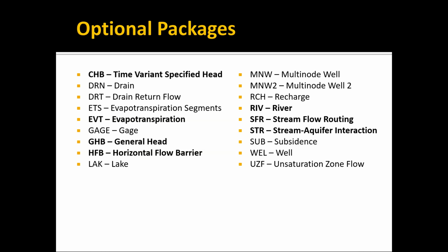If the water table drops too low, it may cut back. Instead of the well going dry, it cuts back the pumping rate. In addition to specifying a pumping rate, you can have a pressure defined well. So instead of telling it how much water comes out, you tell it what the pressure is, the suction on the well, and then it determines how much water comes out. In a lot of cases, you don't need that sophisticated of a treatment, but it is available if you need it.